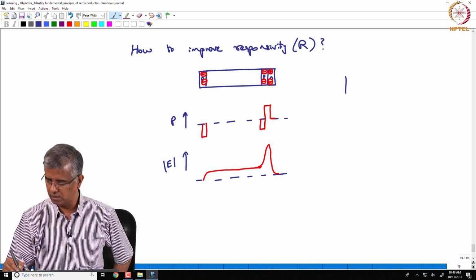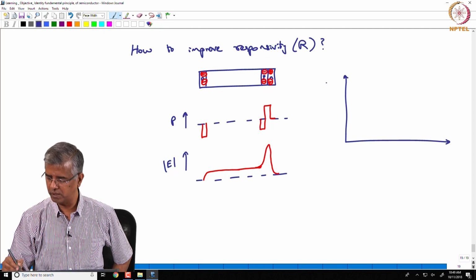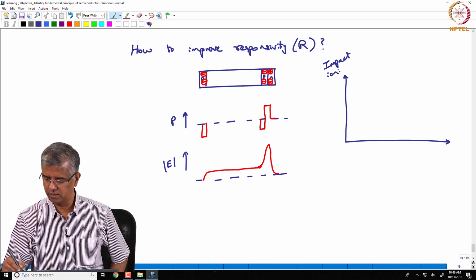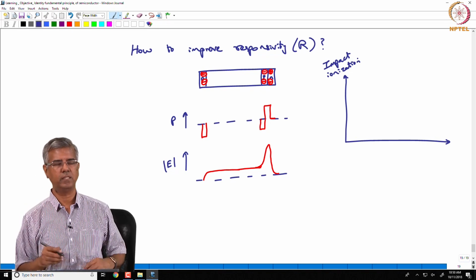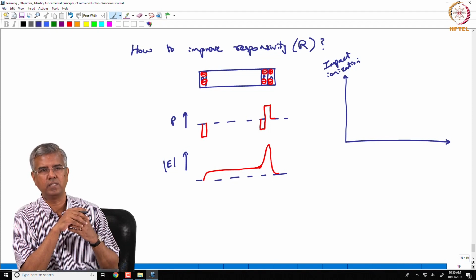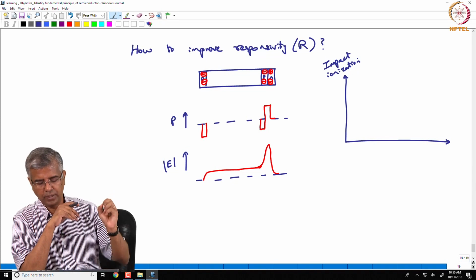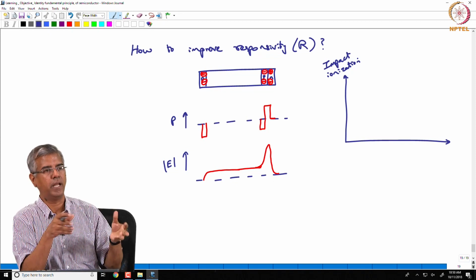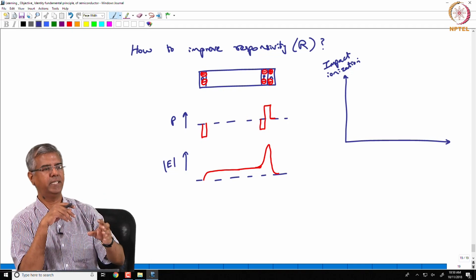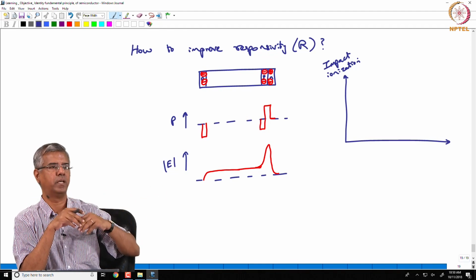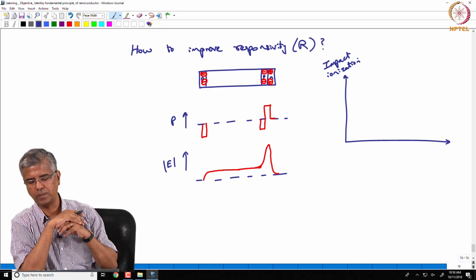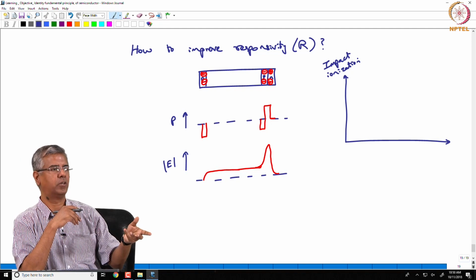Under those conditions, you have a process that's called impact ionization. Basically, these charges have so much momentum, they are traveling at such high velocity that if they collide with any other nearby atom, they are going to just hit it and ionize that atom. So they are going to immediately have an electron pop off from that location, and you generate an electron hole pair.